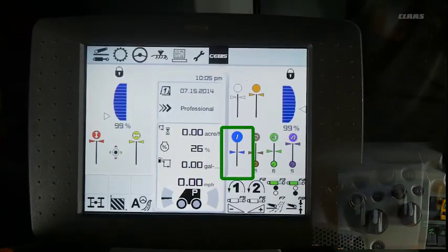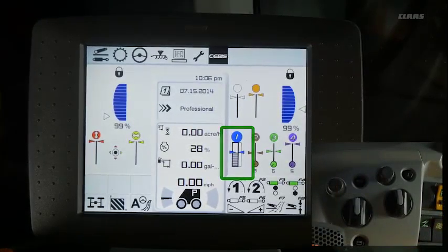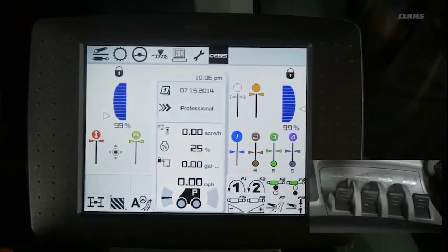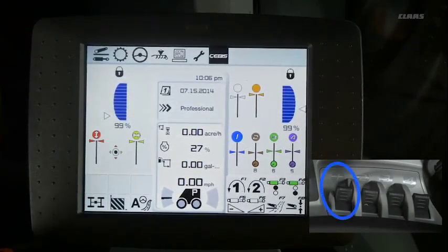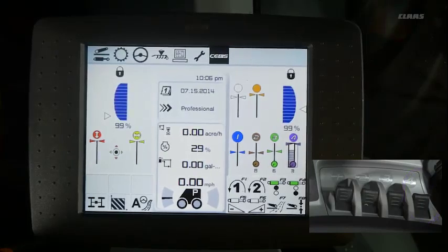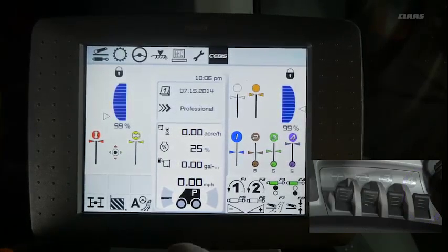Now if we operate the blue valve with the paddle controller and let go of it, the valve will immediately shut off. If the blue valve is pulled to the detent position, it stays on indefinitely, providing a constant flow. It will stay on as long as the blue valve is on demand. Valves 1, 2, 3, and 4, or in this example, the blue, brown, green, and purple hydraulic circuits are all controlled by the paddle controllers instead of the function buttons. As the purple valve is engaged, notice the remote immediately reaches the desired flow rate.